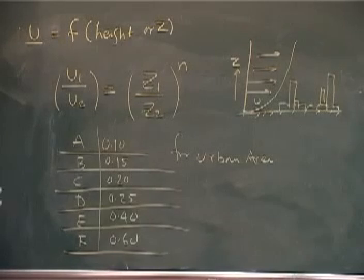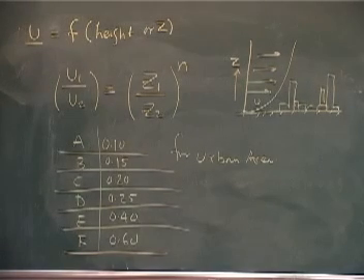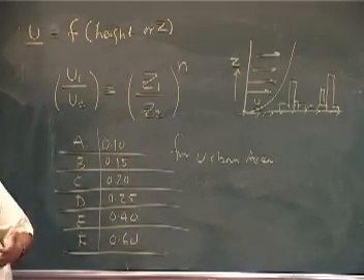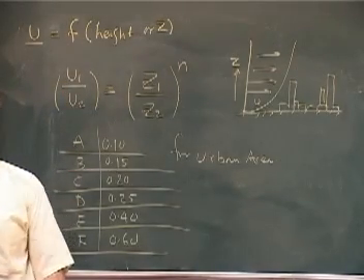So I have given you a methodology or technique. If you know a wind speed at a particular height, you can translate that wind speed depending on the stability that you are talking about, and the area being urban or rural, you can find out the new wind speed. That is what you require in your calculations.